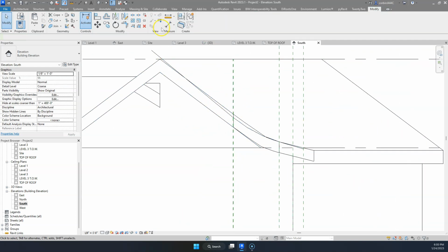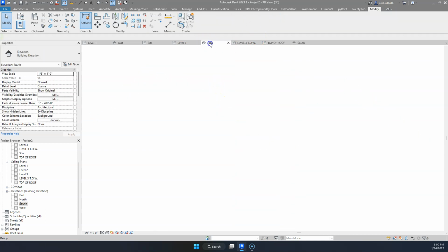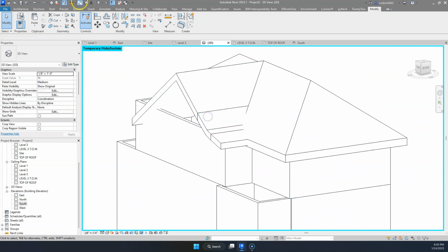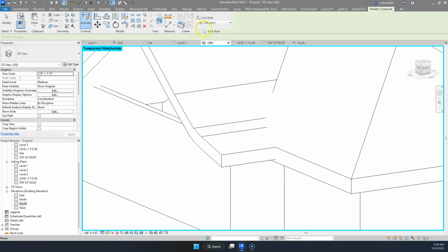So you have some sort of roof by extrusion like that. It looks like it's not quite the right curve, but you kind of get the point, I guess, right? And this line you don't have to worry about, but if you see it in elevation, you can just go here to invisible lines. And where's visible lines? And then just hide these lines.